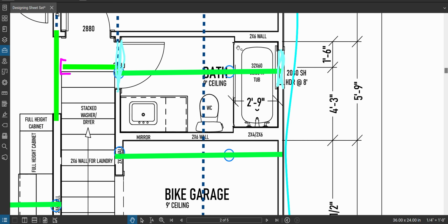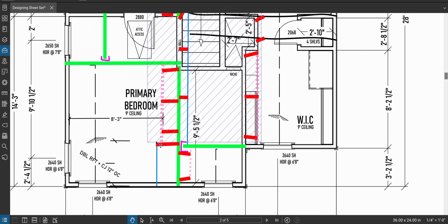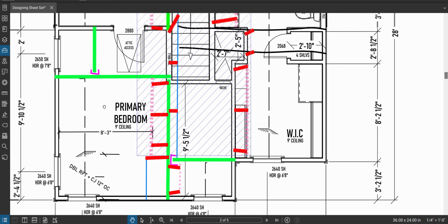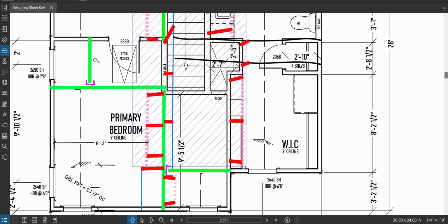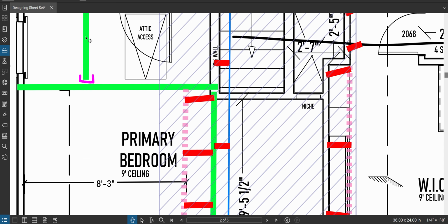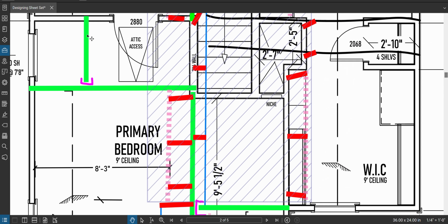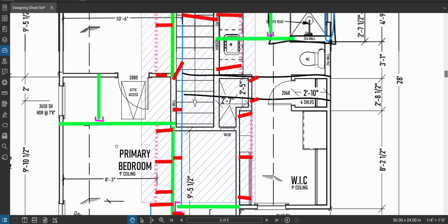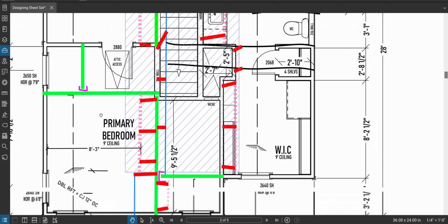All right, so first primary bedroom, let's do this up here. The way you do this is you want to start with the beams that are the lightest, or the ones that are not being loaded by other things, because what's going to happen in the software is once I design this, I can add its load to this new beam I'm designing without having to do any extra math. I just say that it's connected right here and I'm good to go. So that's how that works.